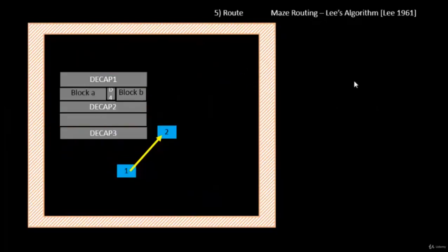We'll remove all the remaining things and keep only this one, because this is again needed, as it acts as a blockage for the routing. For example, there can't be any route that goes like this, over the top of these blocks, and goes to the right side. That's not allowed. So we have to take care of this blockage, this obstruction, as well. For the algorithm, this will be acting as an obstruction. Basically, the coordinates that it sees for this particular set of boxes, the algorithm understands that it can't put any route through this particular obstruction.